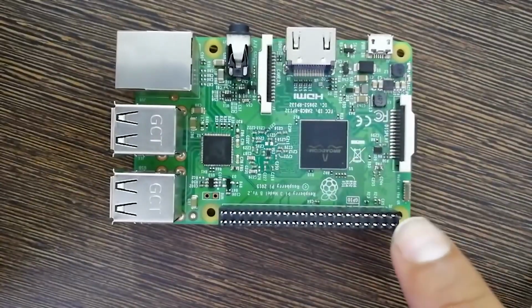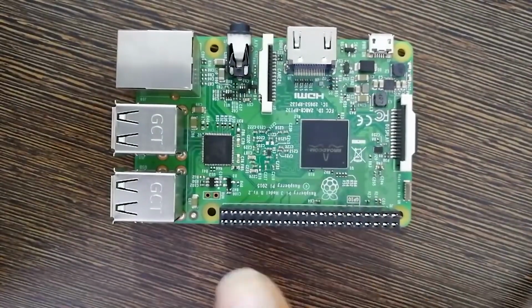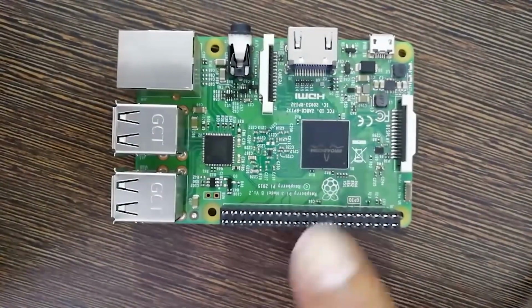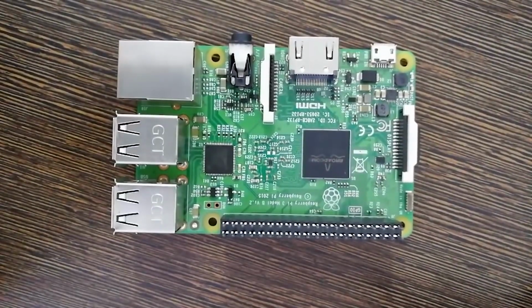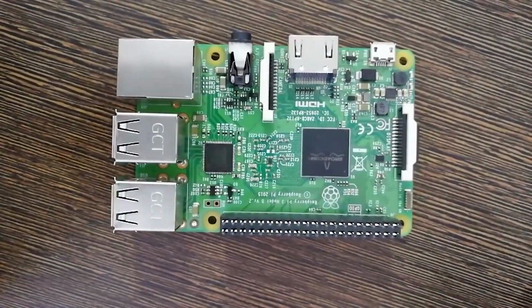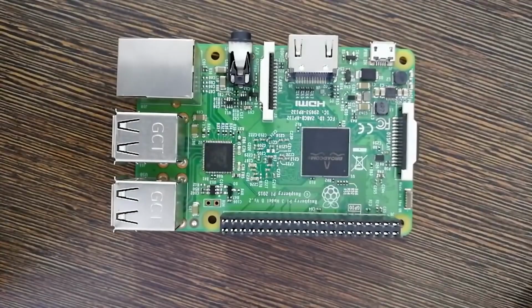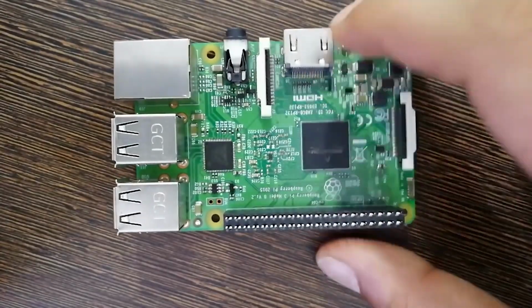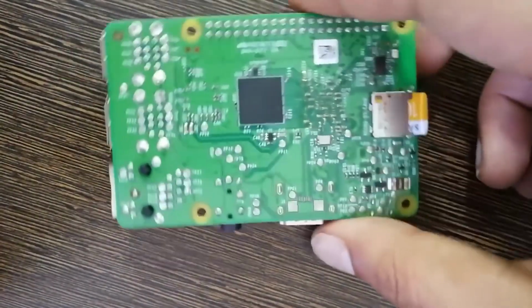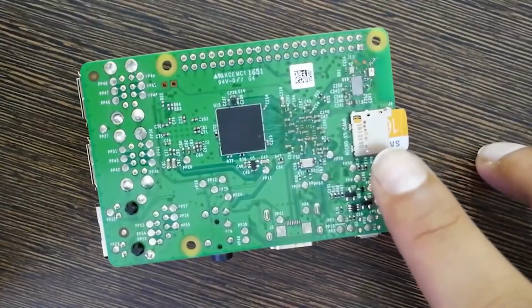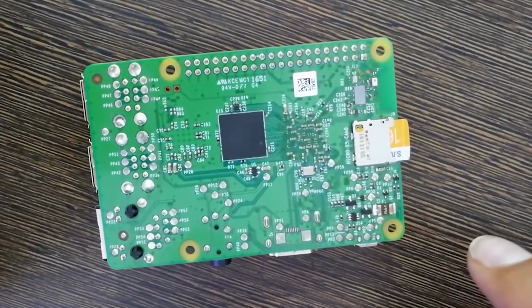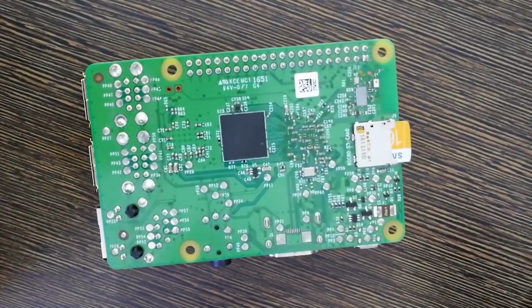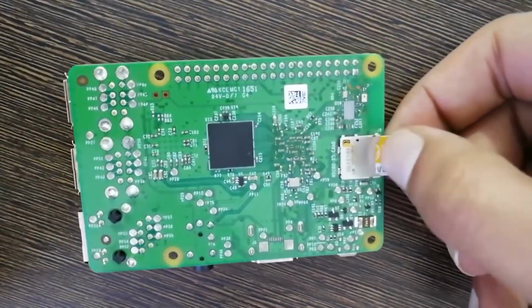When you see here, there's a 40 pin general purpose input output header present. This is something quite interesting and configurable from your Raspberry Pi software, where you can configure what purpose each pin can be used for, which we'll be seeing a little ahead. Now the final thing that I want to show you is behind here. When you flip to the backside, there is a micro SD slot present here. This is mainly to insert your memory card, and when I say memory card, I would generally recommend at least a 16 GB memory card.